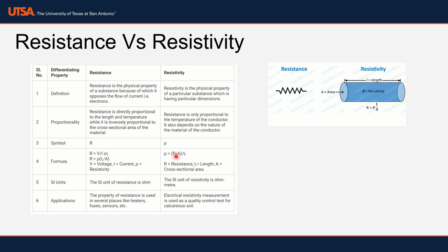And the equation for resistivity is given here, right? So your resistivity is equal to your resistance times your cross-sectional area divided by the length of your wire. Now your resistance is going to be equal to your voltage divided by your current. That's kind of why I showed you that on the last slide. We're going to be doing another lab called Ohm's Law, so this equation you'll be seeing again. But for completeness of this course, I just want to give you the information now.